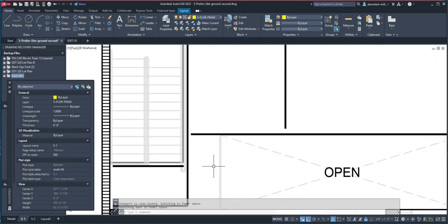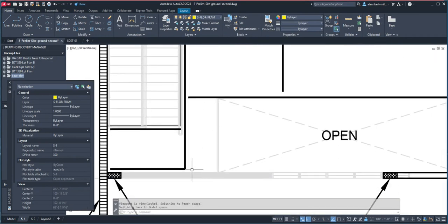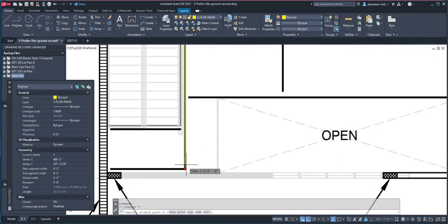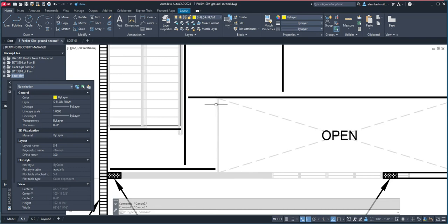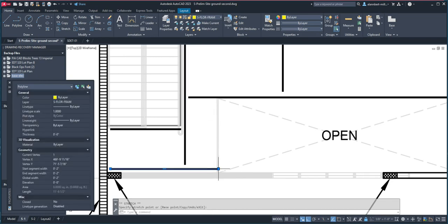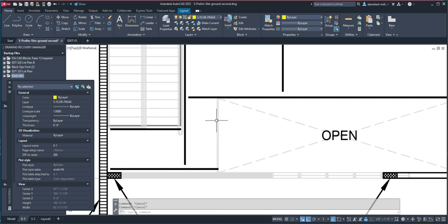And this one also, I forgot this. You know what? We're going to just hold this back, put this forward here, and do another beam here. I can move that a little bit here. So you can see I don't have my O snap on, but I have my ortho. Ortho is the one that makes it go straight, vertical and horizontal.